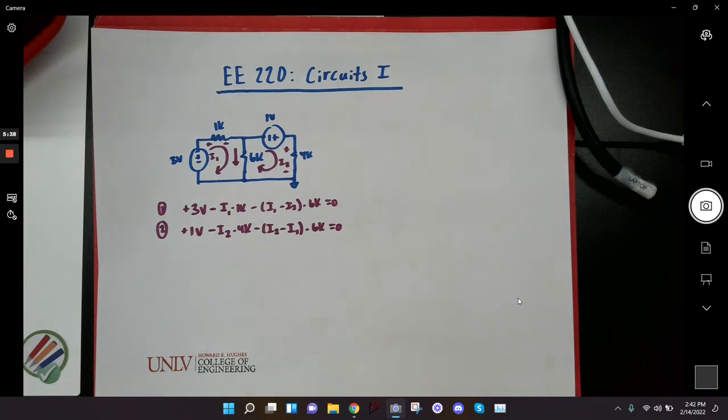Yeah, basically you want to look at when the currents come together, are they going the same direction or are they going opposite directions? And when you have one going clockwise and the other going counterclockwise, then they kind of meet and flow through the resistor together, so you'd add them. But if they're countering each other, then you have to subtract them. Great, thank you. Technically, you can always set up your equations such that they always meet and flow through the resistor together, but you'll just get one of them to be negative, correct? Yeah, exactly. You can always set it up however you want, right?